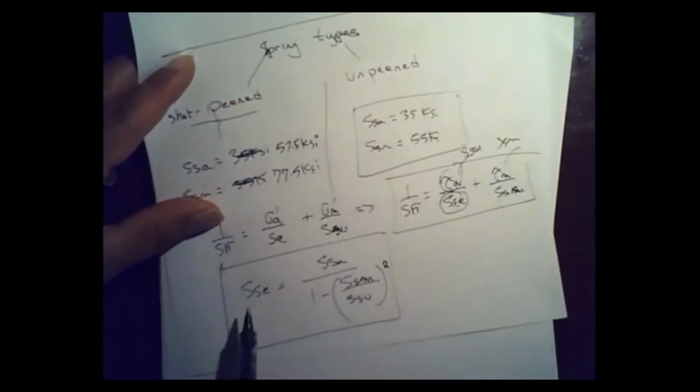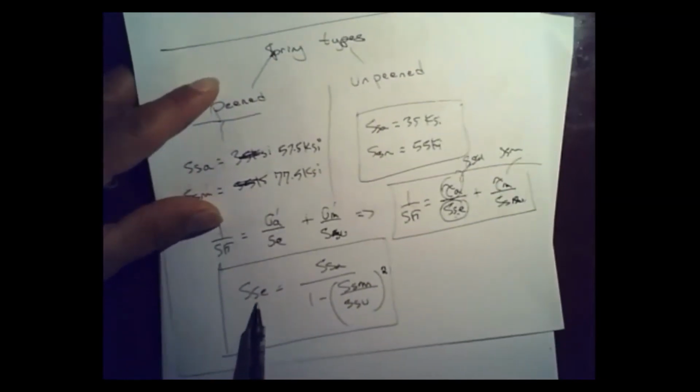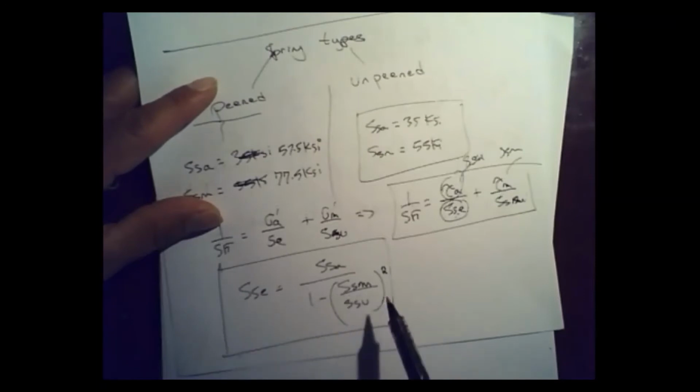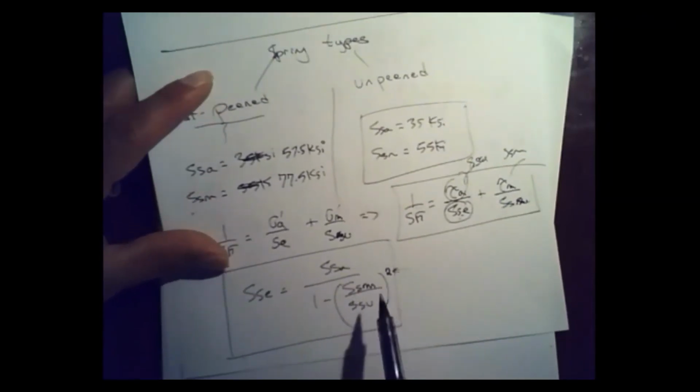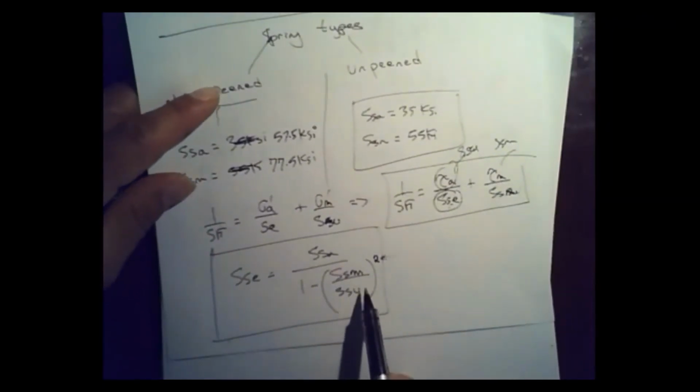And you're going to use these values to calculate your endurance limit in shearing. You would typically use a Gerber criterion. On the exam, I will tell you what to use. If not, then you can use Gerber.